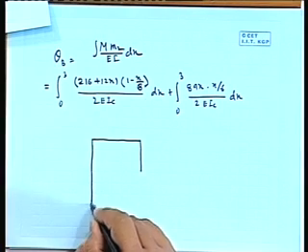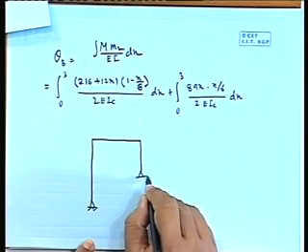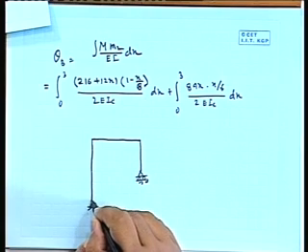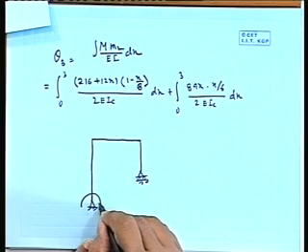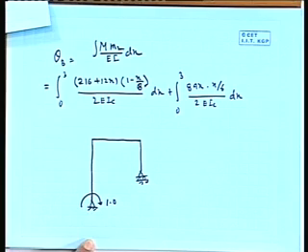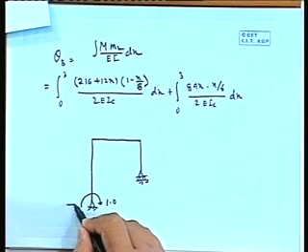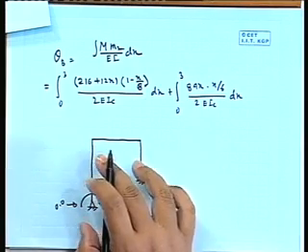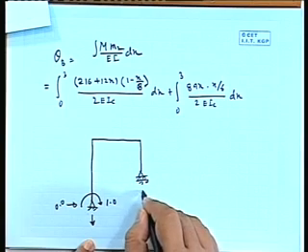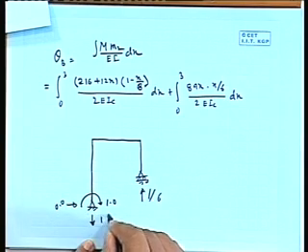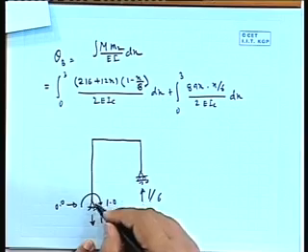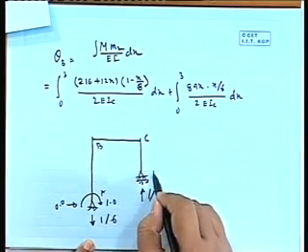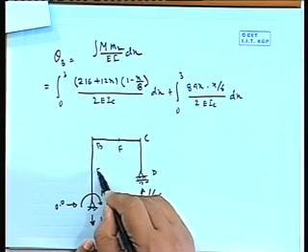Say you are interested in putting the moment here, because we want the slope at A. If I put a unit moment, this force would be equal to 0, and here there should be some reactive forces, 1 by 6 and 1 by 6. Now, this is A, it is B, it was C, it was D, and that was F, and this is E.